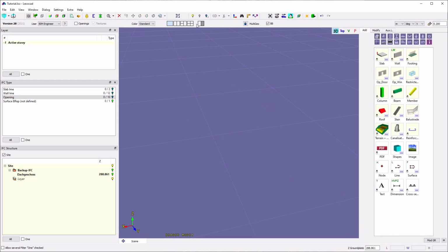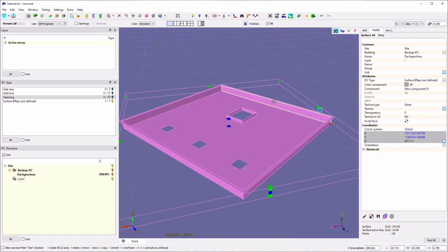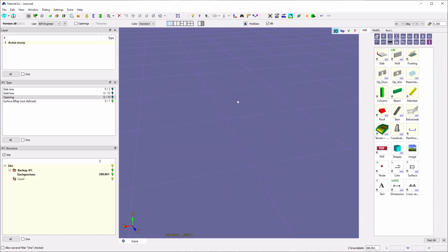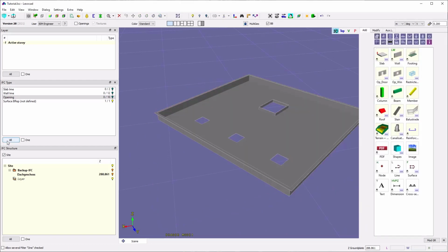When I hide some elements, I can go back to all visible with these buttons here on the toolbar, or the keys for that. You always see the key in green, so you see what button you can use. So with U, I hide the active element. With J, I go back with all elements. With I isolate it. So I can do this also with other elements or more elements.